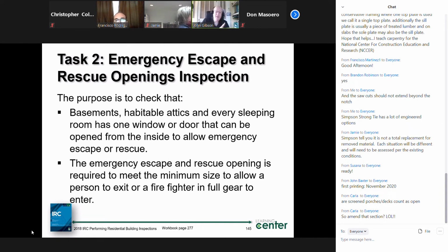I could frame that. But the point being, to get my headroom that I need in there to count as habitable, if I'm having to jack up the roof, or if I have to lift the roof and put dormers on in order to get the headroom, now we've created basically another story up there, and that's the concern. Hinge trusses is what they call them.